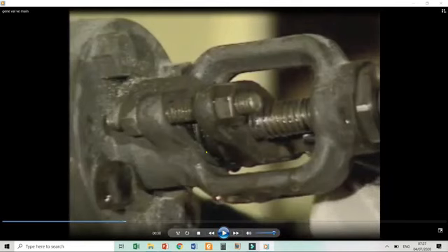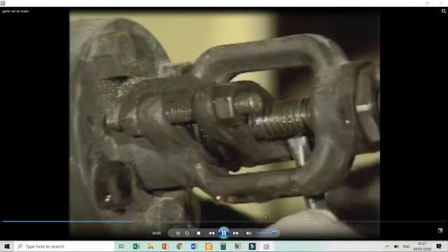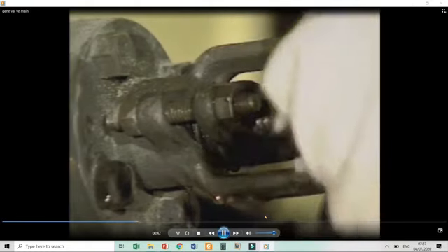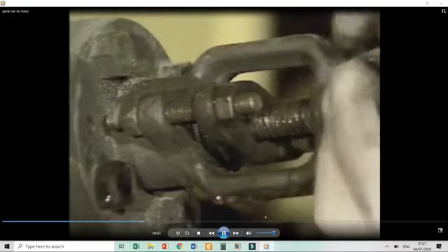As this guy is saying, in industry there is a common practice to tighten the gland nut, or after some time you have to change the packing inside below the gland. But do not over-tighten the gland, it will damage the gland. Usually a quarter turn each at a time. This ensures that the packing gland doesn't become cocked in the stuffing box as the gland nuts are tightened.